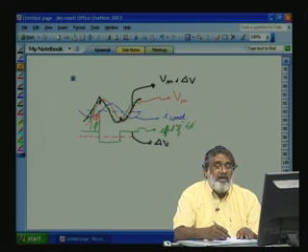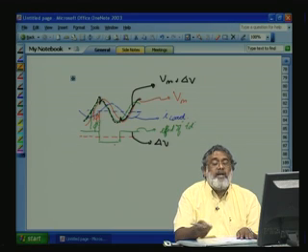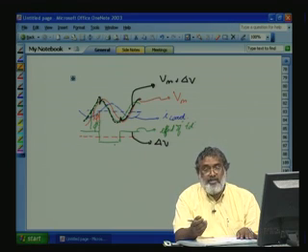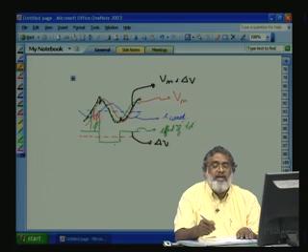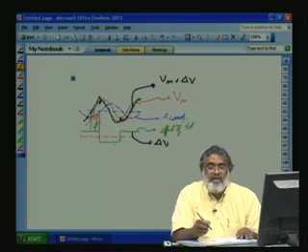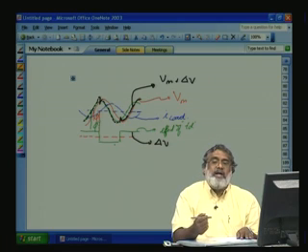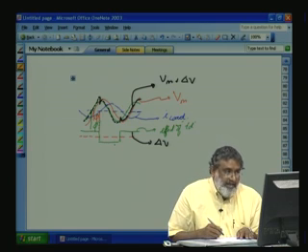Now, apart from the fundamental, due to the effect of the rectangular pulse, it will also contain fifth, seventh, low order harmonics. So even though we are using sine triangle PWM with a large carrier frequency, with the dead time effect, if the dead time is very large, it can introduce fifth and seventh harmonics, and the current waveform, instead of sinusoidal, will be distorted with the fifth and seventh visible. In many applications people think we can give large dead time so that the short circuit is safe, but this is a problem here.